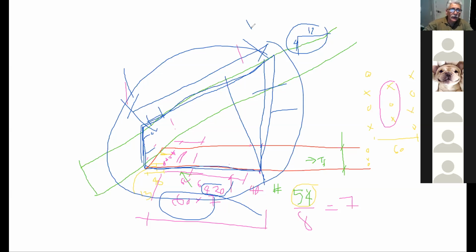And don't forget, Emily, when they're doing this truss, what's going to happen is they're going to set up what they call a jig. They'll start mitering all the pieces of the bottom chord, and the top chord. And then they'll have the whole truss basically fitted together without the gusset plates.